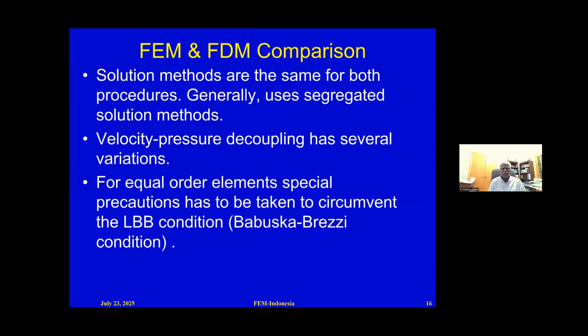Solution methods are the same for both procedures. Generally, they use segregated solution methods. I know many of you in this group, through MATLAB and other places, solve velocity and pressure together. But you can only do that for simple, smaller problems.